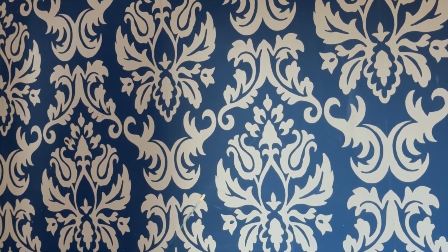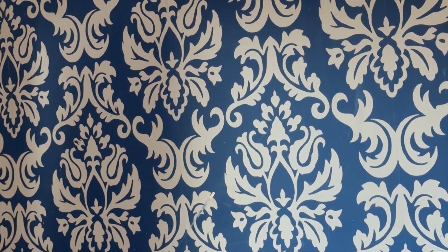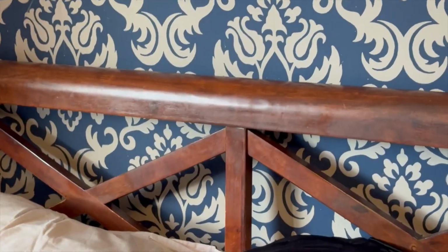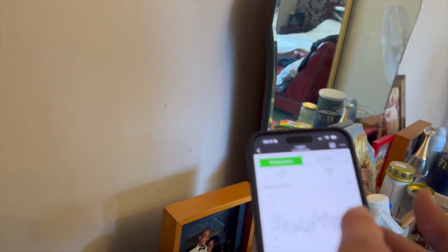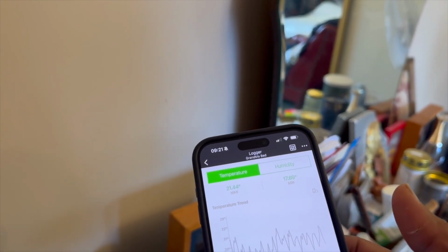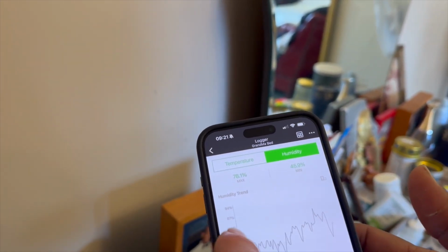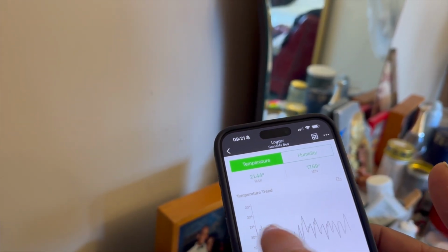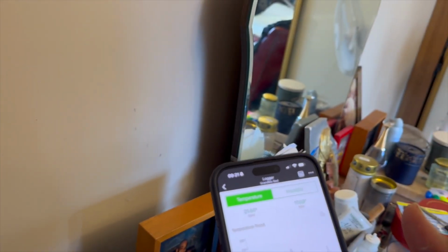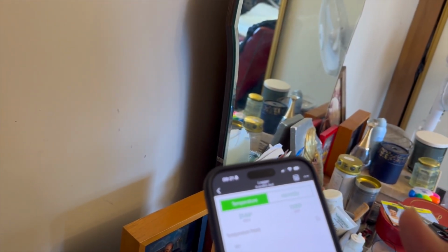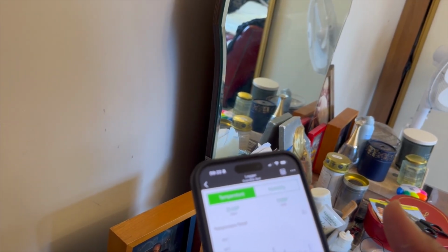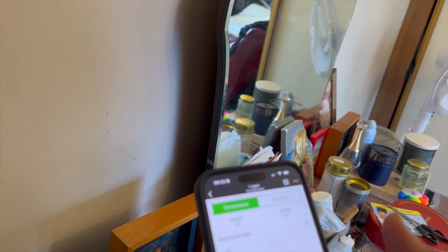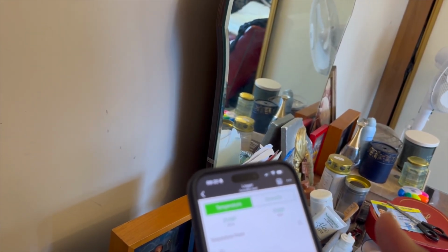It doesn't say the dew point on this, but it takes a bit of time. I'm going to put this outside, I'll do that now while that's doing its bit. It's telling me relative humidity and temperature. I won't go through each one, but the humidity spiked at 87, and at that time the temperature was about 20. You can calculate the dew point very roughly in your head: every 1 degree centigrade difference changes the relative humidity by about 5%. Dew point is where it's 100%.